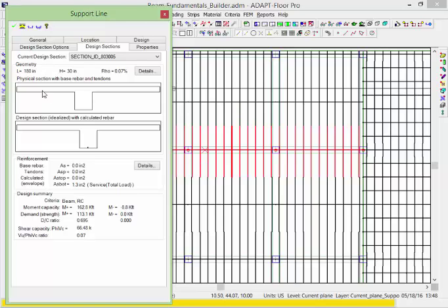And in this case, we have a physical section which cuts through both slab and beam. We have a T section. The program uses the idealized section here in the second image, and it shows a representation of reinforcement needed for that section to meet the demand or the minimum requirements for reinforcing.